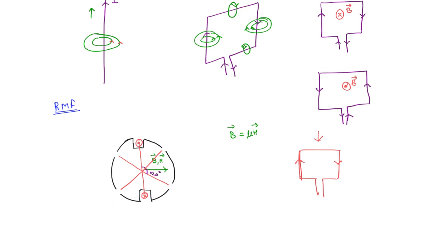So we can place the coils. Here there will be one coil in each of the slots. Now what is the direction of current? If you consider this to be coil A, one side we will take as A, the other side we can take as A dash.